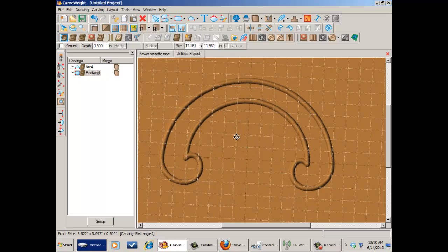Joe, we had a question back here. Someone asked, why didn't we mirror just that one side over? If I'm correct, you cannot join a mirror. Yeah, so a parent-child relationship cannot become fused. They're separate elements, and one is a dependent of the other. So in order for us to apply any of these modeling tools, they have to be one closed shape. So all those lines have to be connected together into one shape. And a mirror wouldn't close it. They'd be two separate elements.